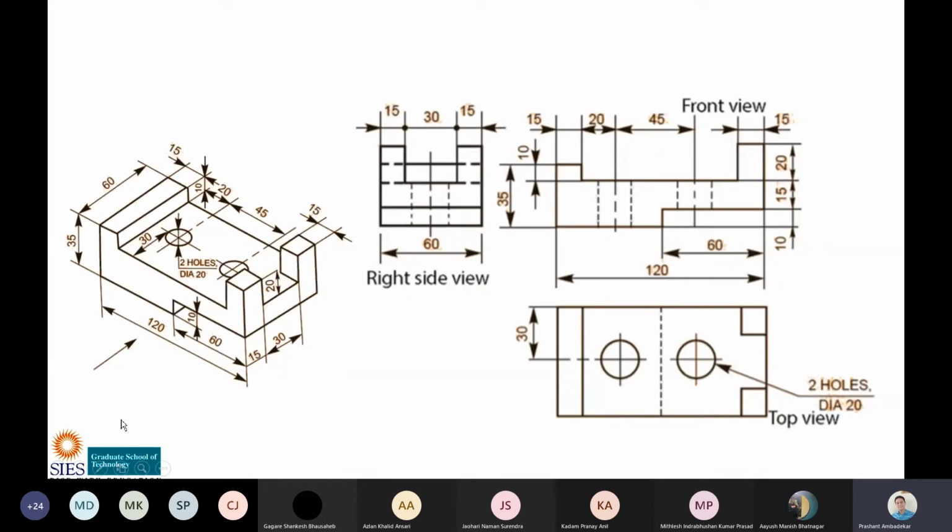In front view we will see this thing like this. Here this surface, and we know the dimensions now, so this will be drawn in front view. See, this is fully drawn in front view like this. Okay, is there anything else in the front view? The height of this and the height of this is the same, so this is hidden behind it. Since it is hidden behind it, it will not be seen, and it is not hidden line either, so this and this will be fully visible. But then there is a cut here, you can see there is a cut here. This pillar is fully visible from the front, but from behind it is not full; there is a cut here. So this will be a dotted line. So you can see this will be drawn as a dotted line here, which is not drawn in this. So there is a mistake.